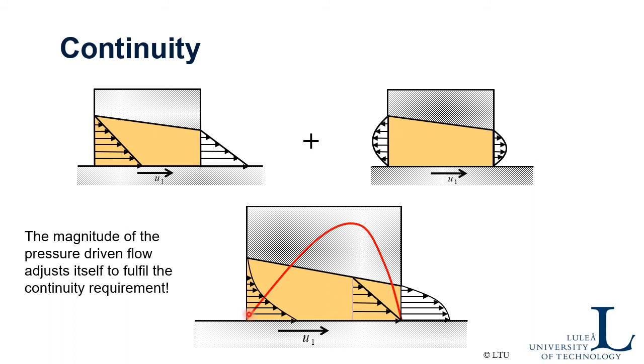So that means that you get a pressure distribution that looks something like this. It is zero here where you have atmospheric pressure in the inlet and outlet, and it reaches a maximum somewhere inside the bearing. And where you have the maximum, you don't have any pressure gradient that can push out the fluid from the film.